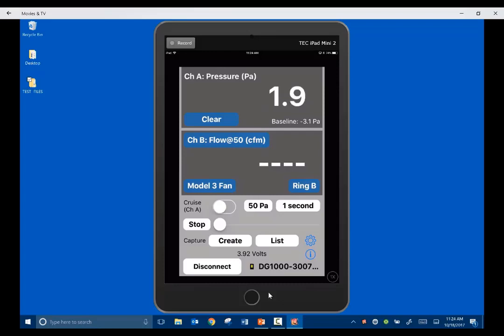This app is also handy for just pressures if you want to have a gauge set up down in the room with the furnace and water heater and walk around the house and turn on fans or open or close doors, turn air handlers on. You can see all the pressure changes with each of those steps. So that's a handy use for it.